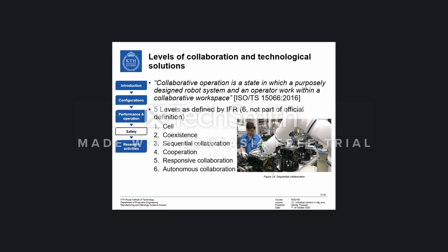Effective presence sensing devices stop all motion in the robot if any part of the worker's body enters the protected zone. They are also designed to be fail-safe so that the occurrence of a failure within the device will leave it unaffected or convert it into a mode in which its failed state would not result in an accident.